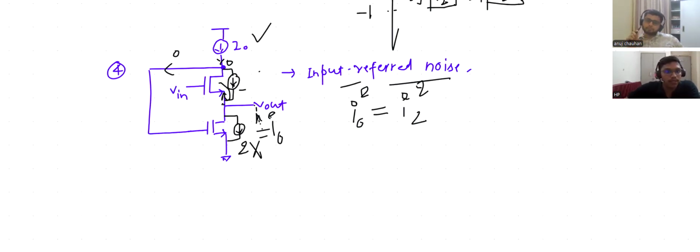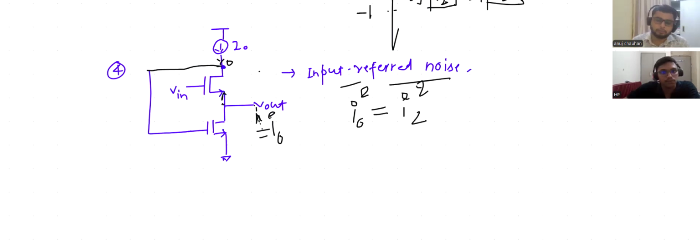Now my target is to find the gain. So I got the noise current. Now I need to find the transconductance gain, so that I can easily refer it to the input. What will be the equivalent transconductance for the circuit that you have to target now?